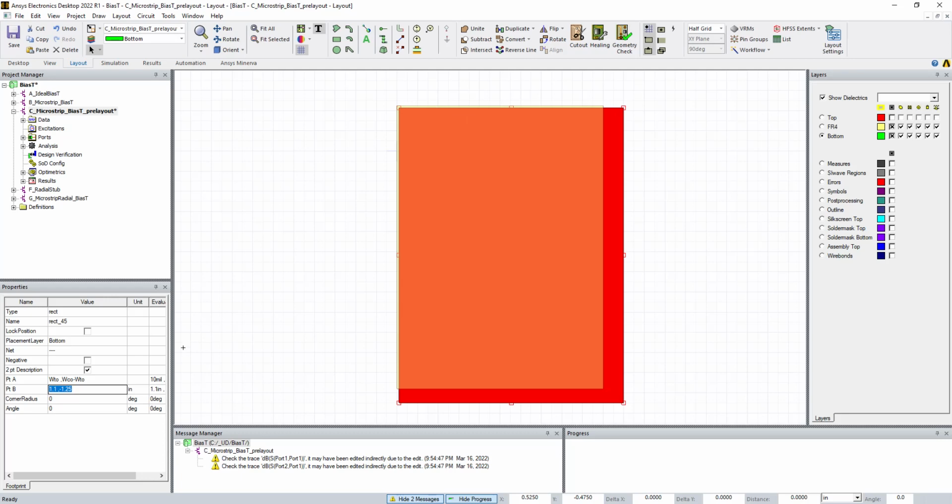So that's there. And then the lower right-hand corner should be the width of the PCB minus the W trace offset, comma, minus the length of the PCB minus the connector offset, because we're in the whole thing, and then minus a trace offset.